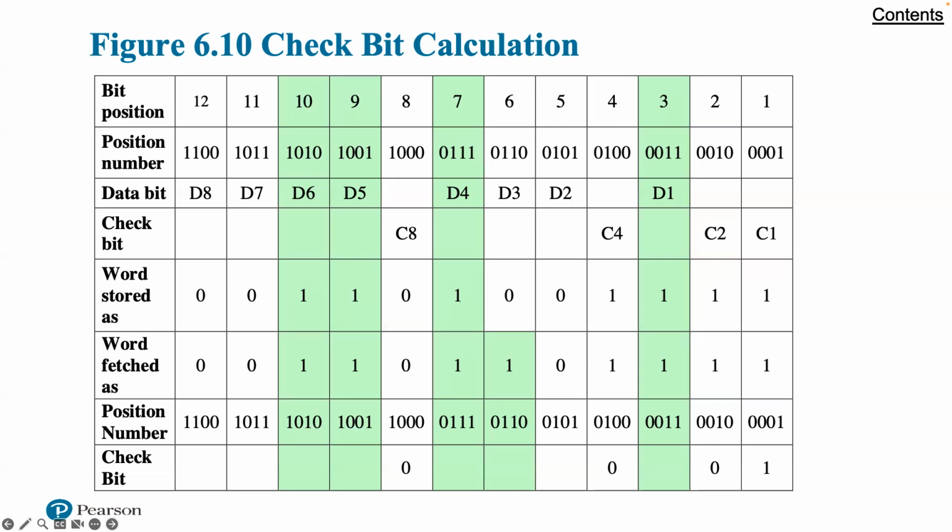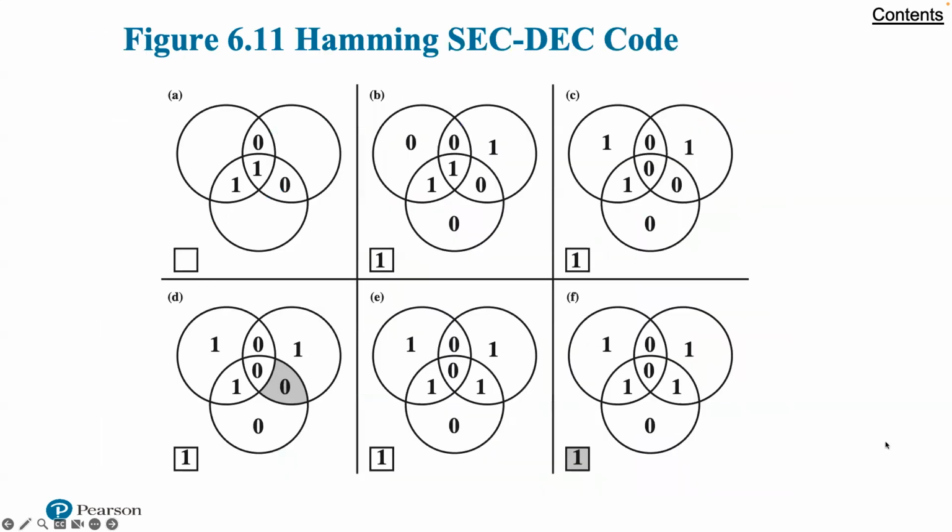An exclusive OR of the Hamming code and all the bit position values for non-zero data bits results in 0110. The non-zero result detects an error and indicates that the error is in position 6. So we were able to find it, and we have an algorithm for correcting it.